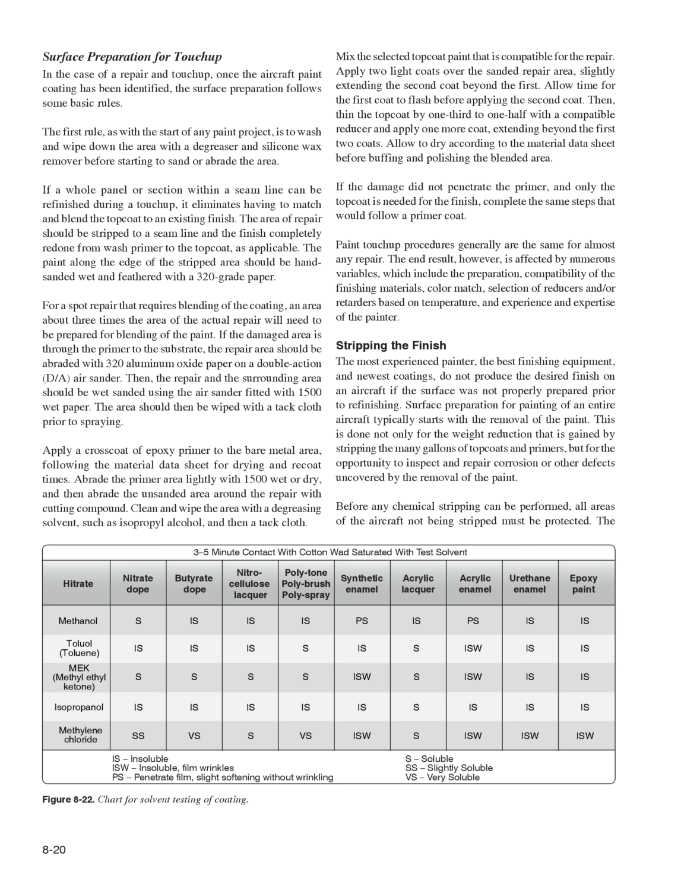If the damage did not penetrate the primer, and only the top coat is needed for the finish, complete the same steps that would follow a primer coat. Paint touch-up procedures generally are the same for almost any repair. The end result, however, is affected by numerous variables, which include the preparation, compatibility of the finishing materials, color match, selection of reducers and/or retarders based on temperature, and experience and expertise of the painter.